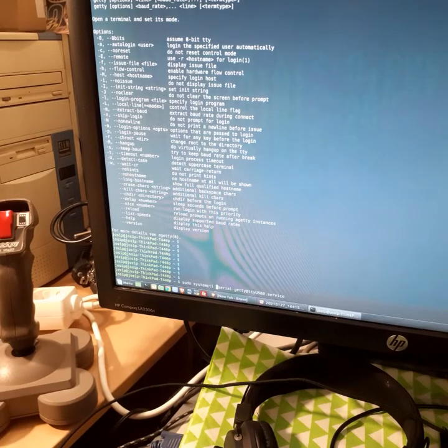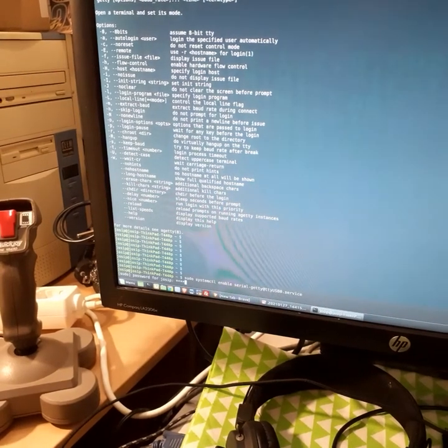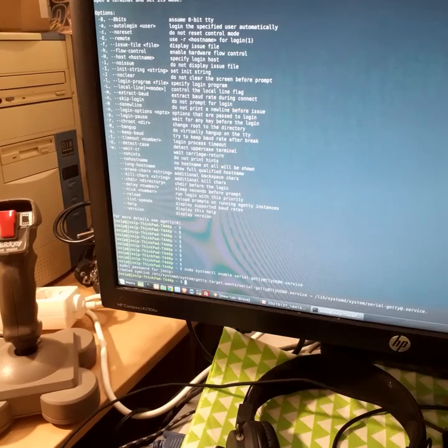First of all, I will enable, we will use systemd to enable and activate the getty on the ttyUSB0 serial port, and okay, password. Okay, so we created the symlink. Okay, we enabled it, and now we will start it.